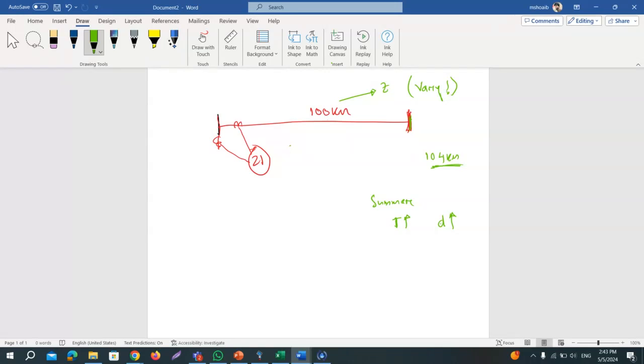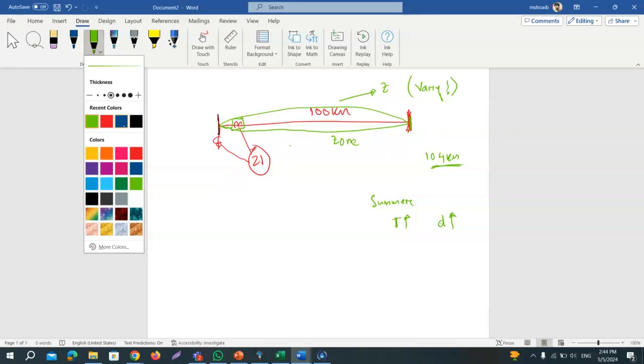So that means, because the length of the 100 kilometer transmission line is not fixed and varies with time, you cannot provide only a single zone of protection. Remember, we covered the protection zone in one of the previous chapters, and we know that the zones are very important. If you provide only one zone, that will not be enough, so you have to provide multiple zones.